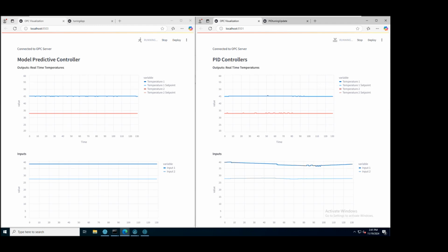And lastly, the control law itself. When we talk about the control law, we're talking about how we actually determine which input should be written back to the plant. This is an optimization routine, which means that we determine the best set of inputs based on the current information that we have to achieve some objective. And this objective really could be something as simple as, how do I track my set point in the best way possible?